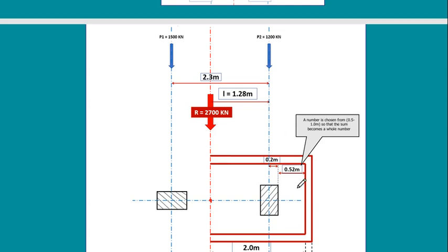And what about this distance? This distance is the protrusion of the plain concrete out of the reinforced concrete. What is the protrusion? It is equal to the thickness of the plain concrete. It is given here that the thickness is 30 centimeter. So I know that this is 30 centimeter. So this number is the only unknown I don't know. And we said that I'm going to take it something between 50 centimeter and 100 centimeter. Then I would start with 50, start with the small one.